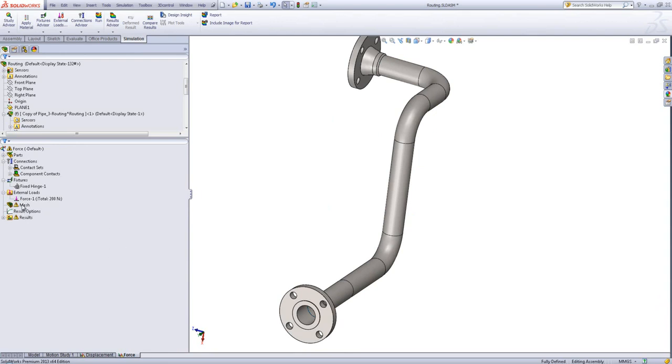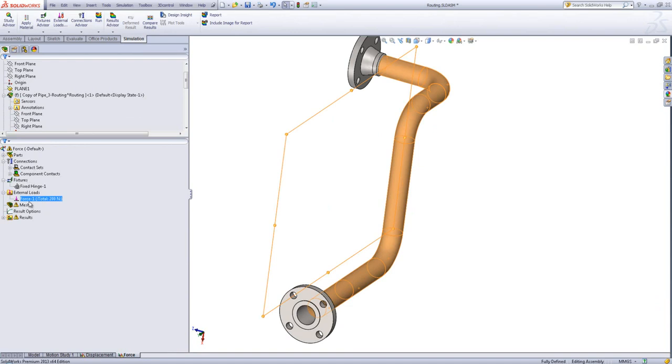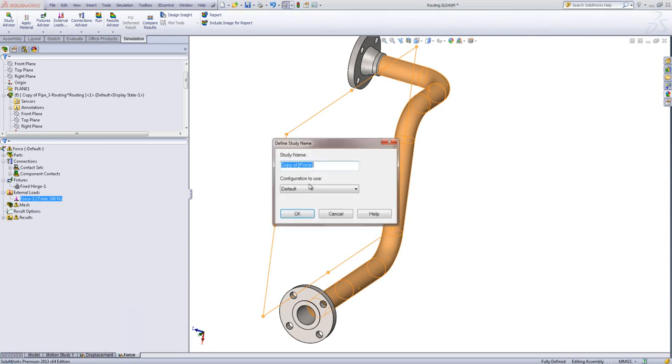So the mesh is already set up, we've already specified that, we've already got our fixture and our force, our contacts are already set up. So now you can see we can very quickly start appending to our set of studies. And so that's that one good to go. What we can then go ahead and do is duplicate that again. So let's call this one gravity.